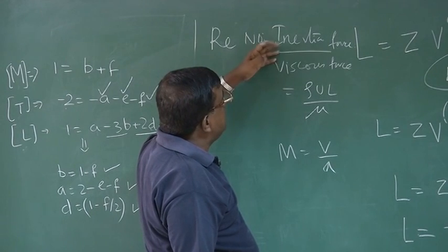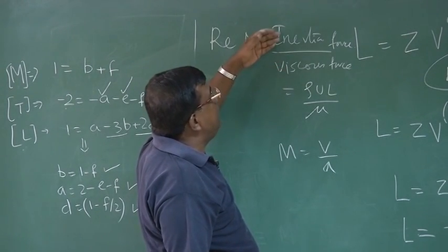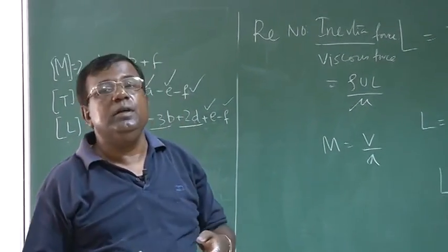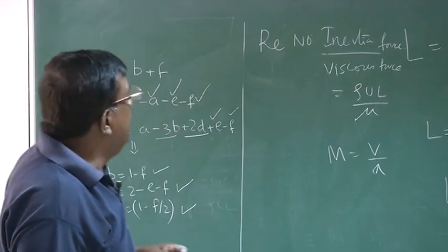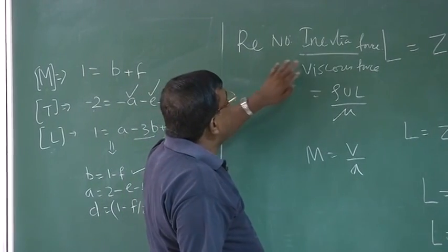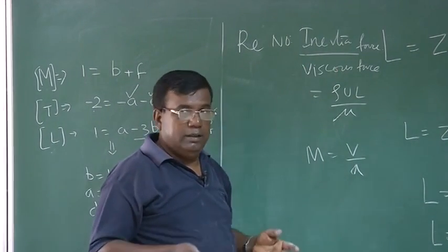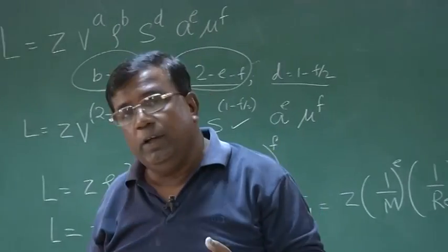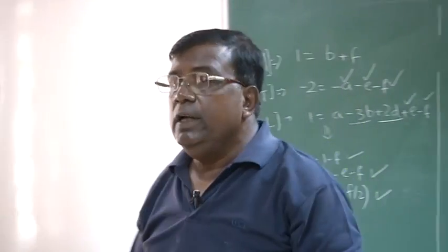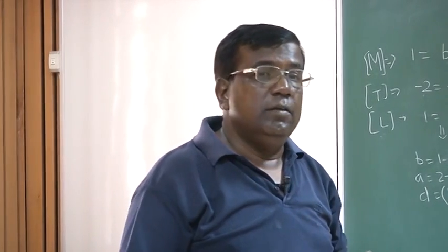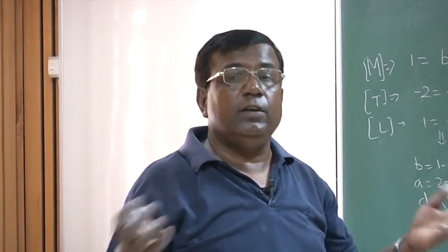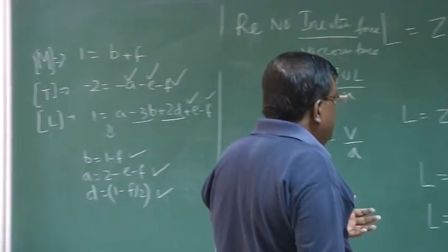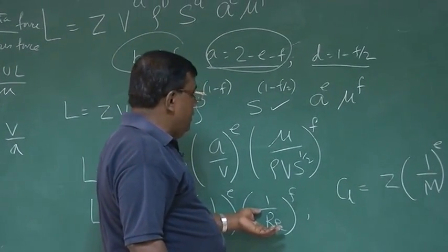then in a relative sense, the viscous force is less compared to inertia force. That means when I am analyzing the flow, the viscous effects will be minimal. If Reynolds number is low, then it is very clear that the viscous force effect will be more dominating. And it is true, if I want to get the pressure distribution over the aerofoil or the wing, it is important how viscous it is. If it is highly viscous, that will have a larger effect on the redistribution of pressure through shear stress and all. So very important non-dimensional parameters we got, called Reynolds number and Mach number.